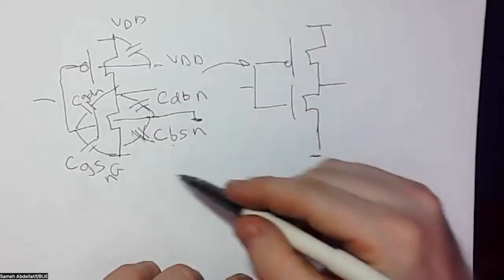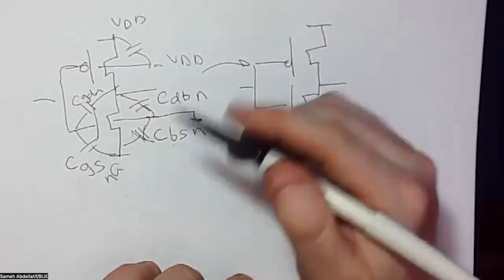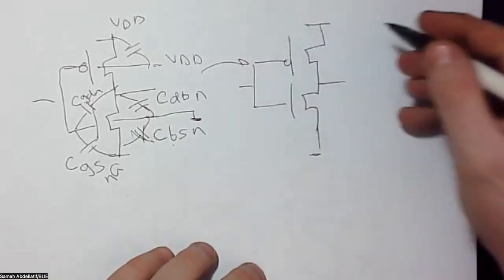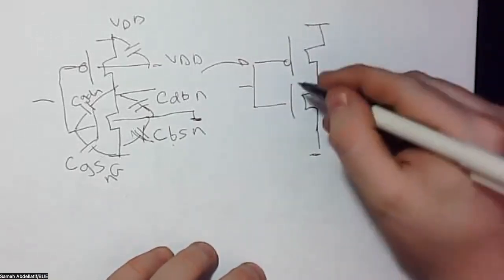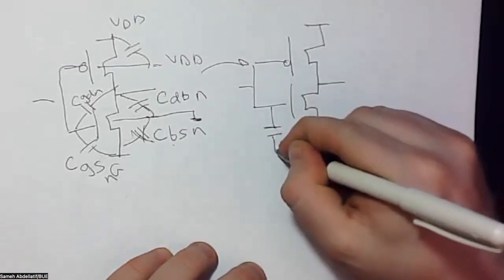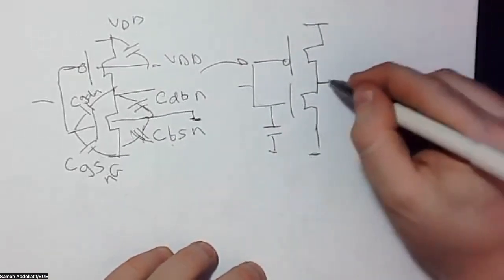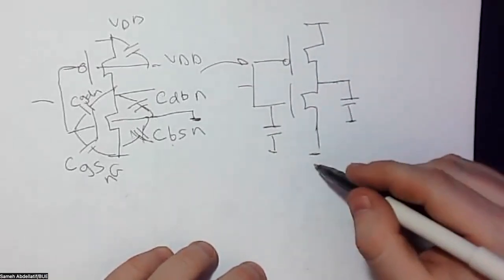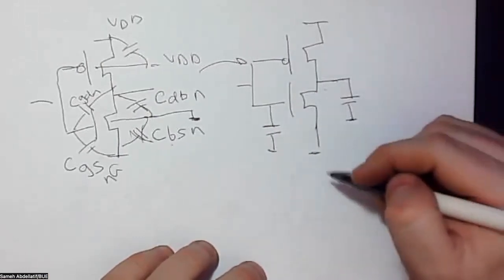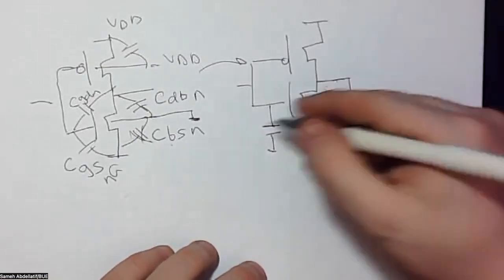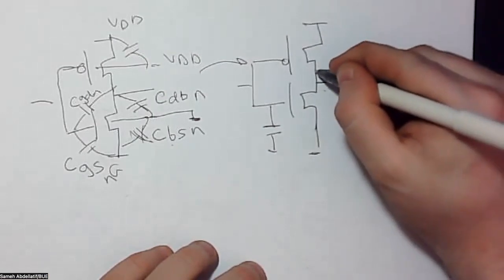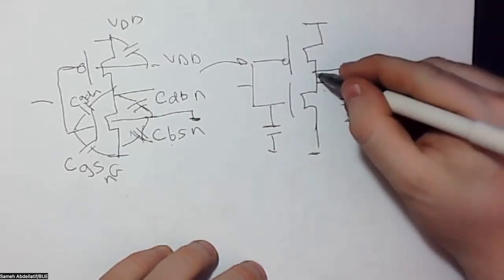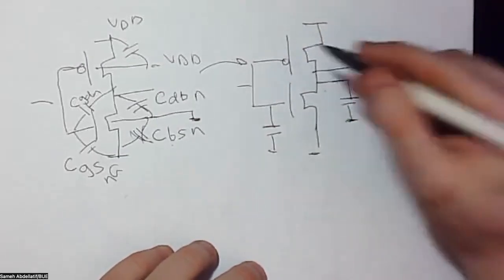So instead of having these interconnected capacitances, we are going to analyze the capacitance in a simple way so that, by the end of the day, we can have one capacitance here to the gate and one capacitance here to the drain. As I just mentioned, the capacitances to the source and to the body are not of interest because both are grounded. And similarly, we can have another capacitance here. This is for the drain of the PMOS.